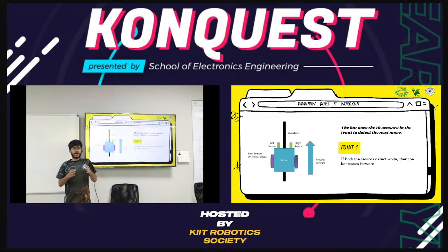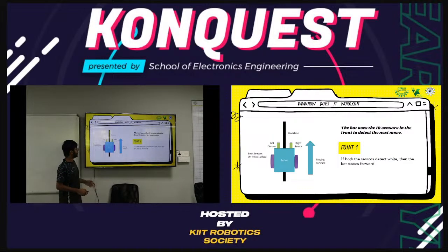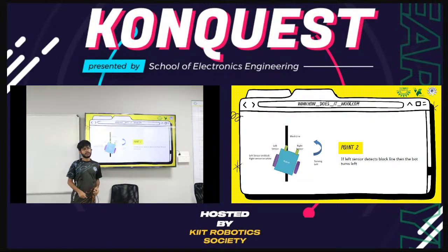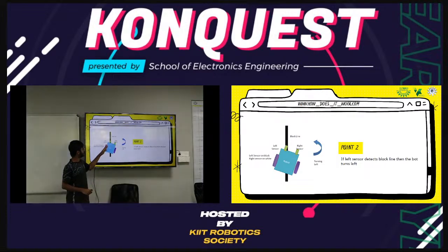All right. So what is to be done then? If your path is straight, then none of the sensors will be touching the line. Then you should be moving your bot forward. That's what we have done over here, right? The bot is moving forward as a result. But what happens if the left sensor is touching the line? So we must correct that, because if the left sensor is touching the line, that means the line is bending left.